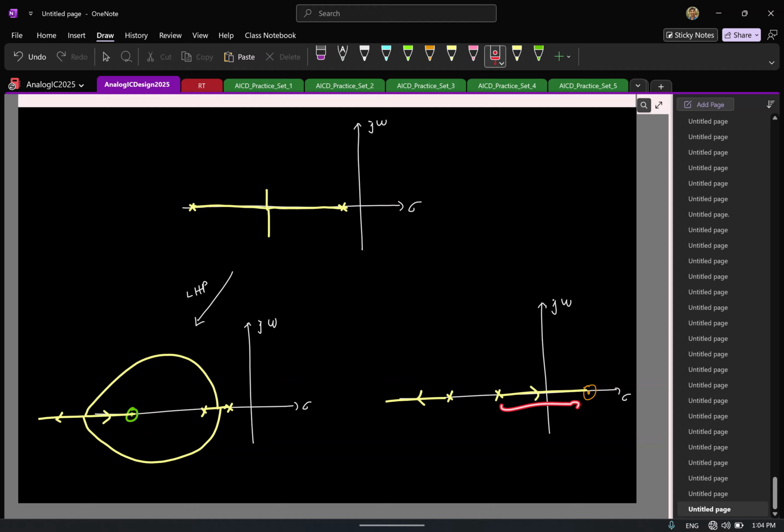You see, one pole is actually entering the right half plane, right? Which means you are actually well off without doing anything. When you didn't do anything, you had a case like this. You had 2 poles sitting close to each other happily, making sure that the poles never entered RHP. But in the act of trying to do something and helping the system, if you introduce an RHP 0, that is a huge problem. So this is an RHP 0.